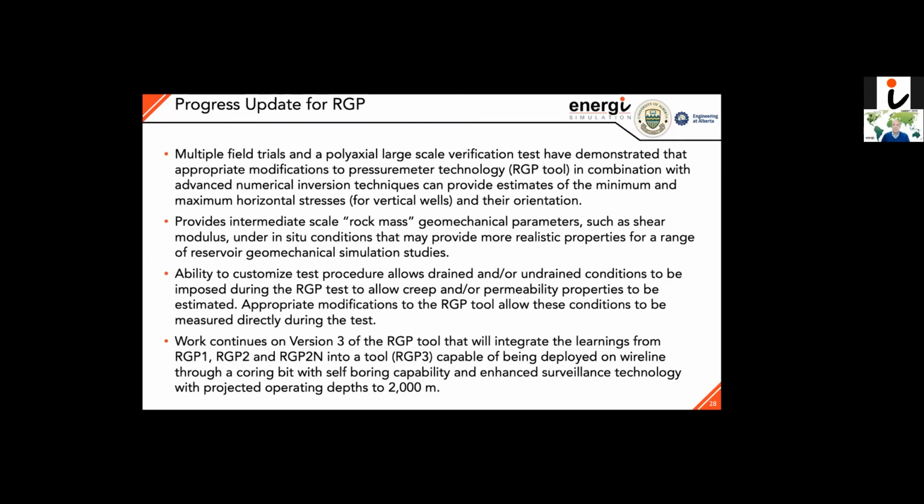Didn't get a lot of chance to talk about it today, but there are some really exciting abilities to control how you do the test, drained, undrained. You can make certain measurements around transient permeability, pore pressure responses at the boundary during the test. You can do hold tests. You can determine creep properties. Some really exciting conditions that you can impose during the test procedures to extract the kind of data that we need for many of the studies that you've talked about.